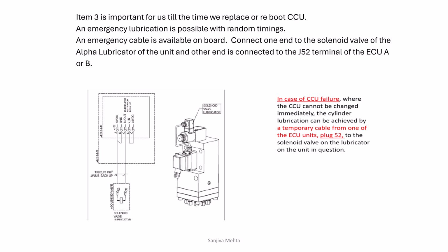All right. How to reboot the CCU? I told you earlier. Put the power off, both the powers off, A and B, the two sources, UPS and ship backup, battery backup and UPS. Both sources put off and put on again. If the system revives, sometimes it gets rebooted. If not, then you replace it.